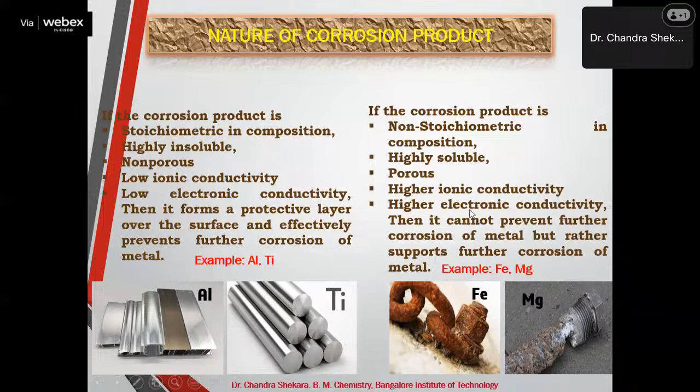And hence, in these active metals, iron, magnesium, sodium, zinc, lithium, we observe corrosion as per their electrode potential value. Here the rate of corrosion is directly correlated to the electrode potential value of the metal. In active metals, the rate of corrosion is exactly in the electrode potential value order.